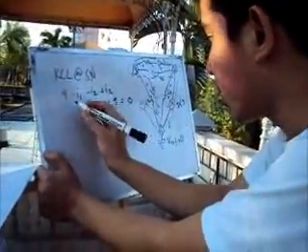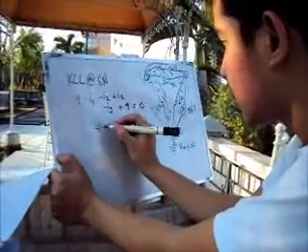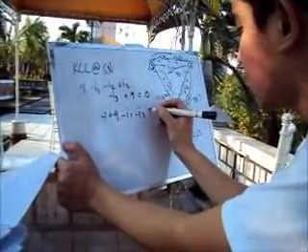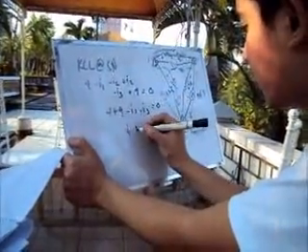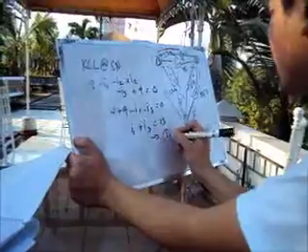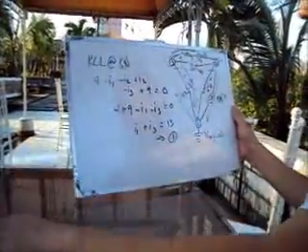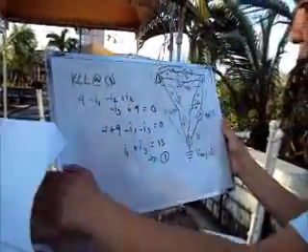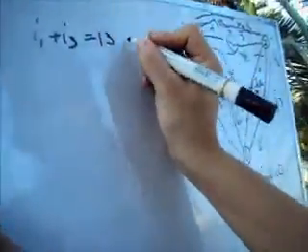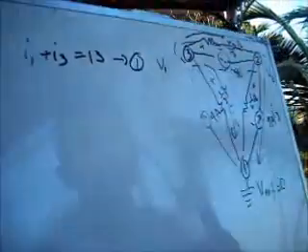So let's reduce the equation. 4 plus 9 minus I1 minus I3 is equal to 0. So I1 plus I3 is equal to 13. So we have our equation 1 for solving the circuit. Next, we have our equation 1, I1 plus I3 equals 13. We have two unknowns.